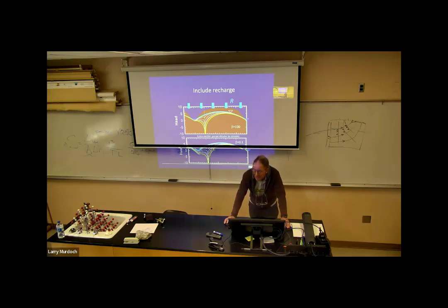So in a very idealized case, the stream acts like a constant head boundary, so the head change from the well can't make it past the stream. But in reality, it can. It could do that because of low permeability material on the stream bed, or just because of low permeability between the aquifer and the stream. Okay, so wells can affect the ground on the other side of the stream.